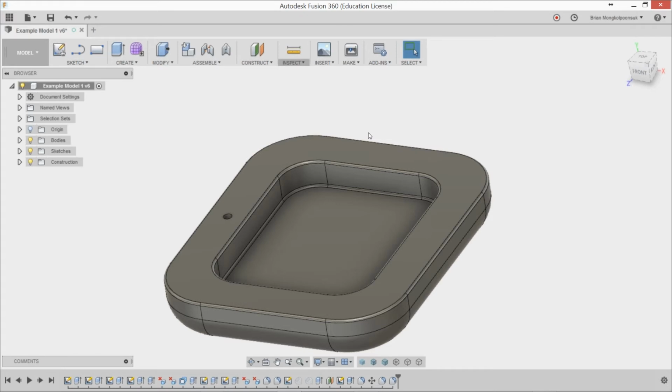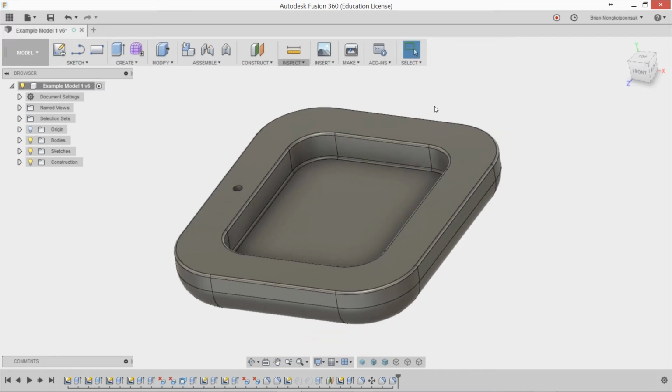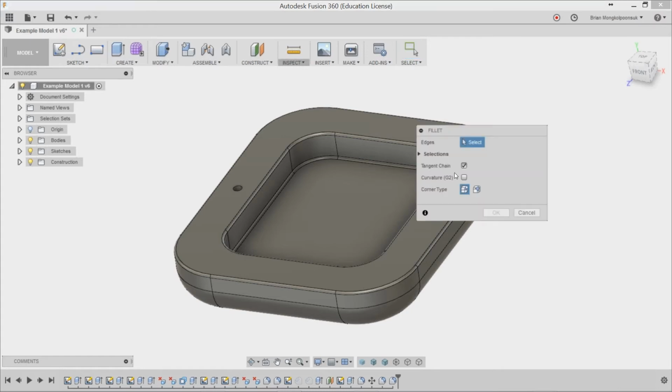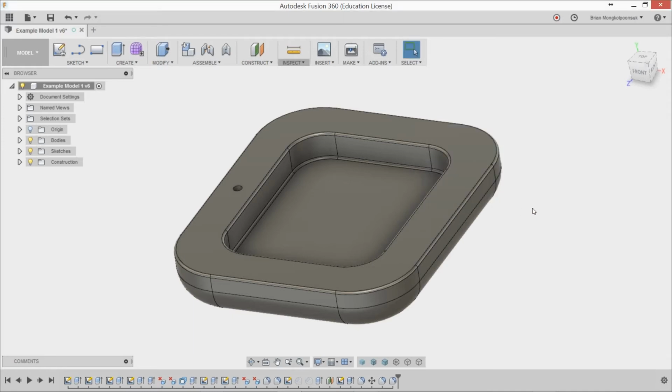Also, during that point too, guys, you can have different fillets in there as well. I believe it was last week when a customer asked for a tapered fillet. So you also have the option to select from the drop down, once you select an edge, which kind of fillet you want to use there. Right. So next, let's look at another feature.